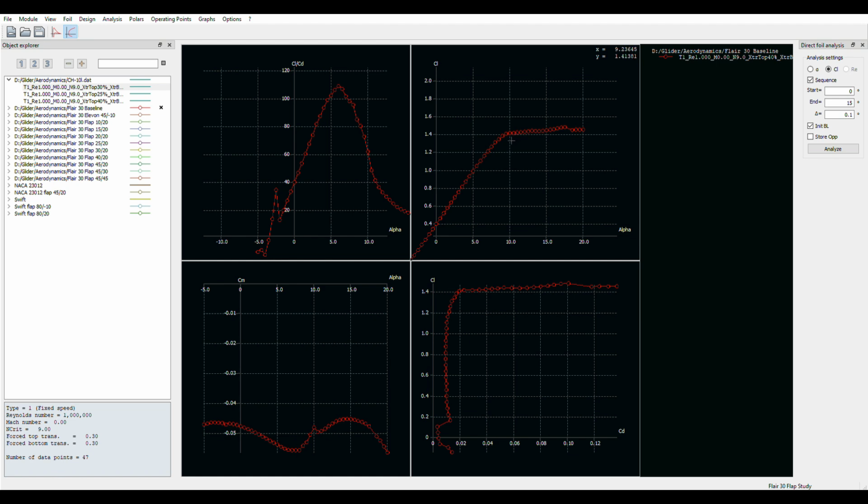And when I first saw this, I thought, well, that's not very good. I know my airfoil goes to 16 degrees, way over here. I don't stall till I get way over here. And at first I didn't know where the Swift was, but I now know where the Swift lies, and it's even better than this one. So it's a kind of wimpy stall angle of attack, and I suspect that's because of how they positioned the transition point being well aft and how they did the pressure recovery.